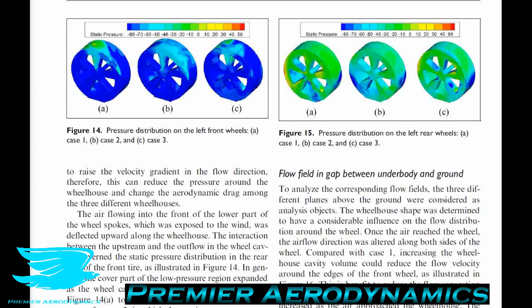The pressure distributions give us very good indications as to how much drag and lift are being produced by the wheels. All we need to do is look at the pressures on the front and back of the wheels, and at the top to get a decent idea of the drag and lift productions respectively. If we look at the front of the wheel and we get really high pressure, then that indicates there's probably going to be more drag than if there was low pressure. And if we get very low pressure on top of the wheel, then that indicates that we'll get more lift.